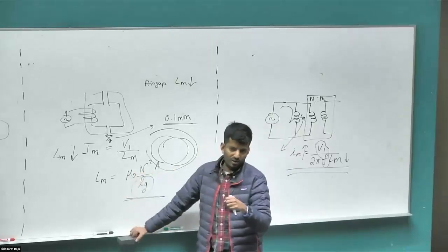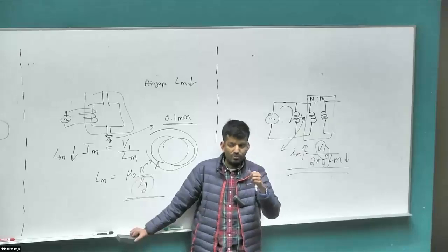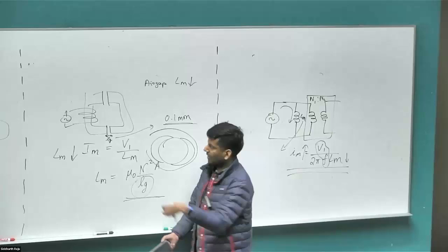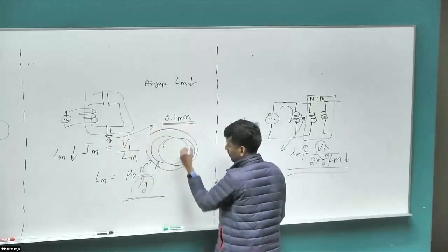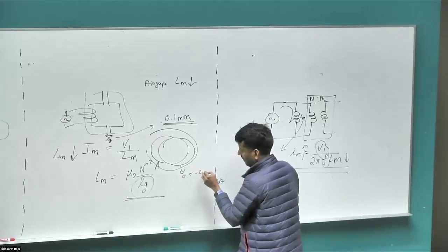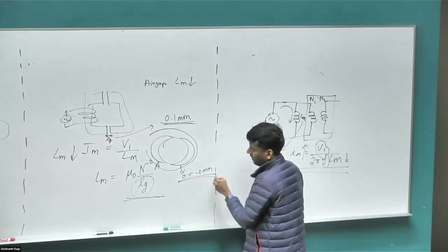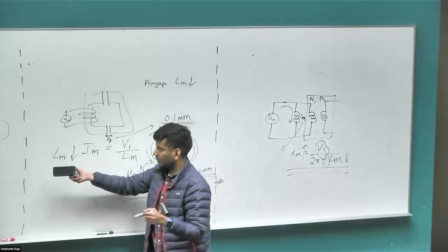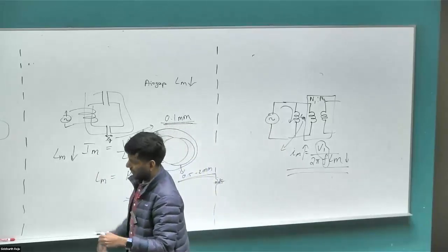We have solid rotor bars. You can tighten them so effectively that as it rotates, there is going to be no stretching on the rotor bar. So you can get this length to be quite small for an induction motor, but for a permanent magnet motor, this will typically be around 0.5 to 2 millimeter. Right? But in an induction motor, you can get this so tiny that the inductance is relatively small, and even in that case, you would have like 20 to 30% of the current being the magnetizing current.